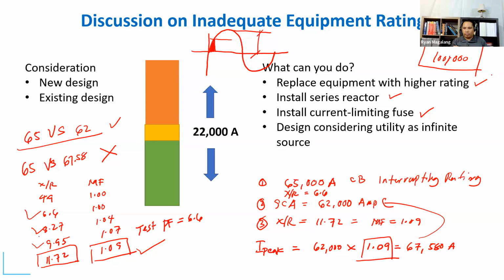Most of the other devices are 35 kA and above, while these few pieces are 14 kA. Somebody must have just gotten something from the hardware store and put it in there, thinking, oh, it fits, without doing analysis. So that's one thing.